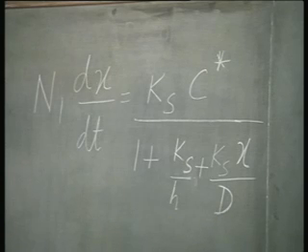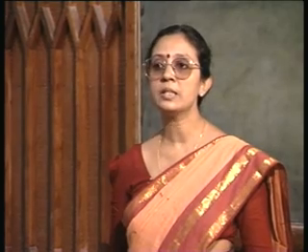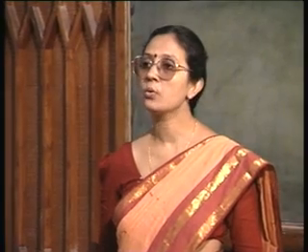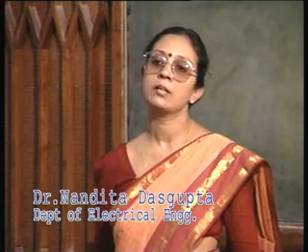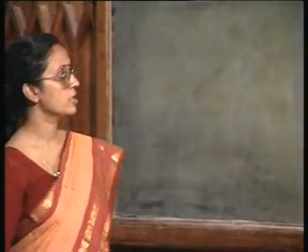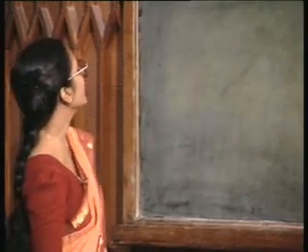So, this is the differential equation, and now we must solve this differential equation in order to obtain the oxide growth rate characteristics, that is how does the oxide thickness increase with time. Okay, it stands to reason that if you carry out oxidation for a longer time, the oxide thickness will increase, but how exactly does it increase? That is the point where this equation is going to help us. So, very simply we can start by transposing.